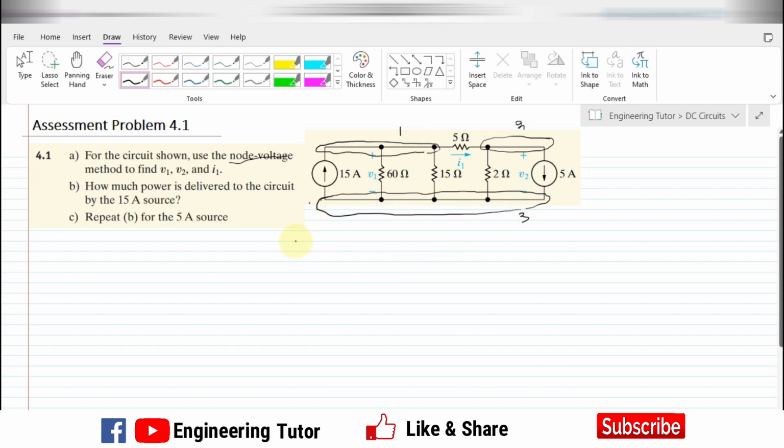So what will be the procedure? Here we have to select one of these three as a reference node. Which one should we select? In many questions, the node where most of the branches are connected is selected as the reference node. So here we will select node 3 as the reference node.